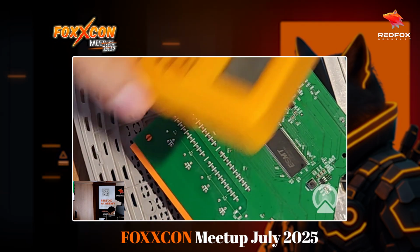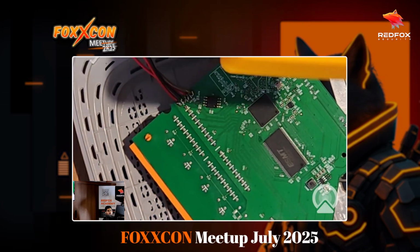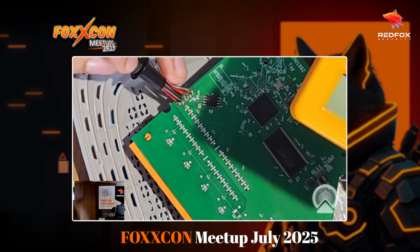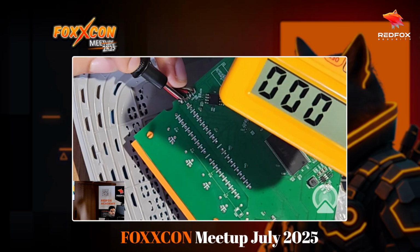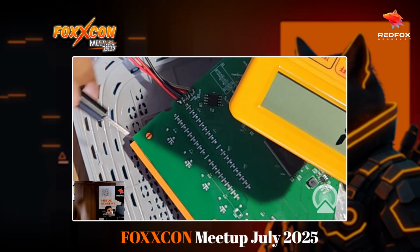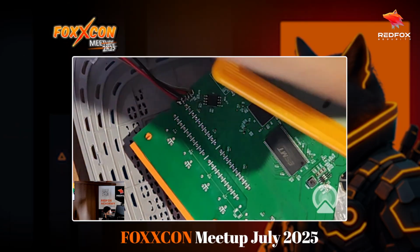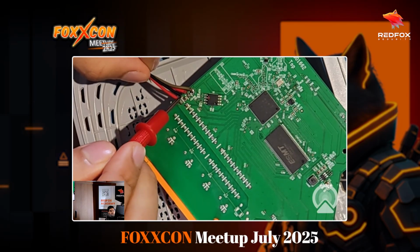Can you hold this here? So whenever this is connected, you see it beeps. It shows 000 and beeps. That means current is flowing between these two wires, and these two wires are connected both to ground. Okay, so now we know that the black one out here is ground.